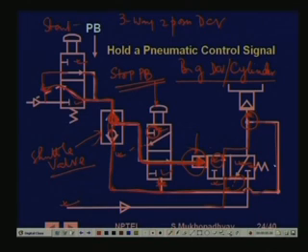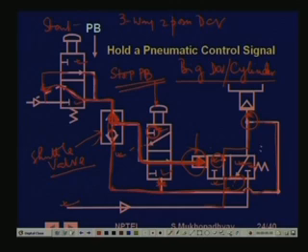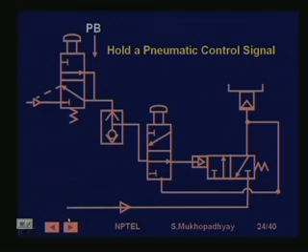So, basically this is a kind of latch, something like the auxiliary contact of a PLC logic or a latch in digital logic. Even if you release the start push button, the pressure at this pilot port will be held, and therefore, this valve will maintain in this position, and the pressure at this main load port is going to be maintained. So, this is one application which seems interesting. Basically, such things are realized using pneumatic logic.